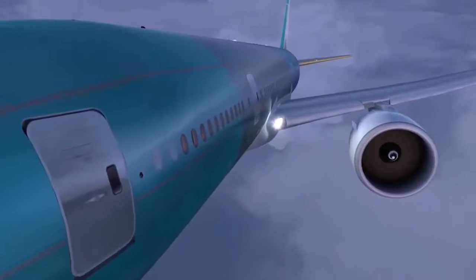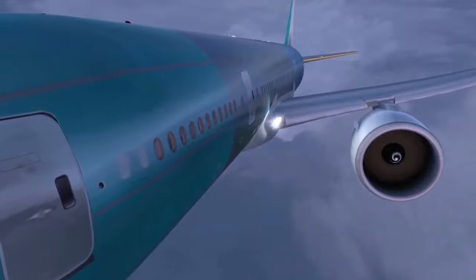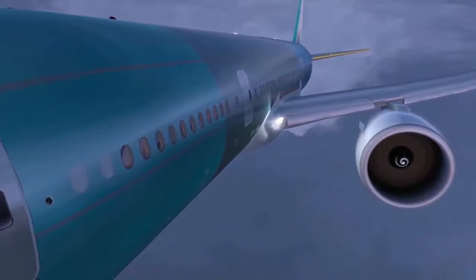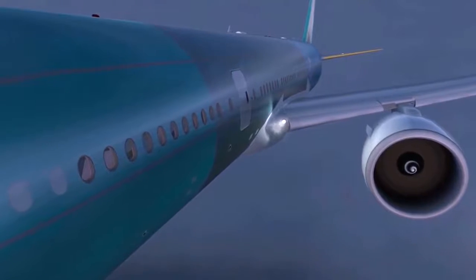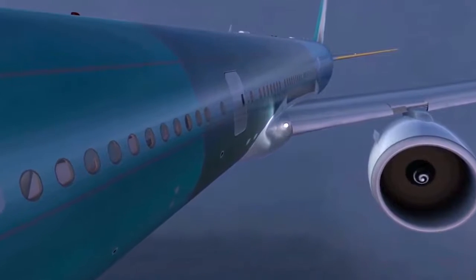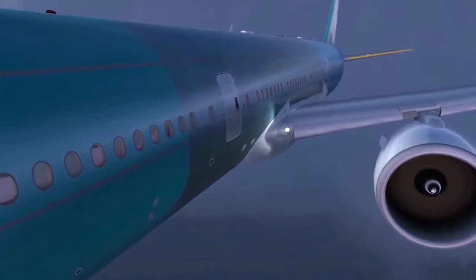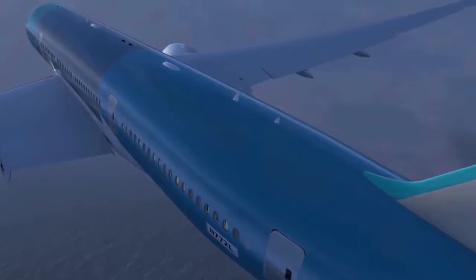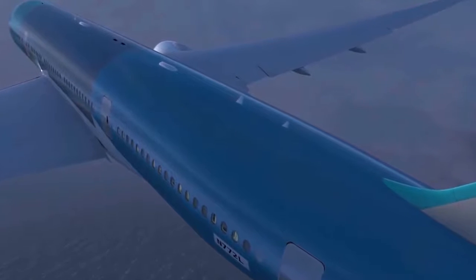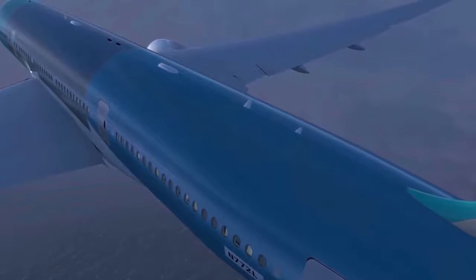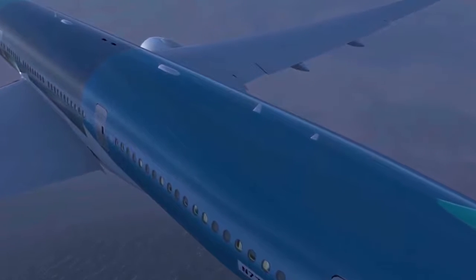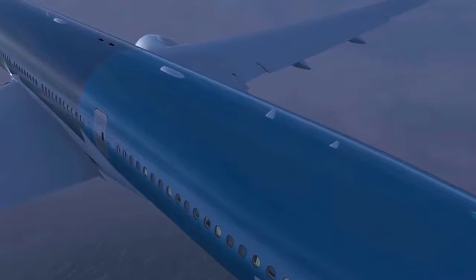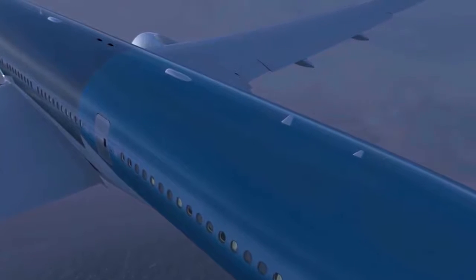When the aircraft starts descending and has descended at least 1,000 feet below cruise altitude, the ASCPCs command the descent mode. During the descent mode, the outflow valves gradually open to give a smooth change in cabin pressure. Target cabin altitude is set so that the cabin pressure value is slightly higher than landing field pressure.